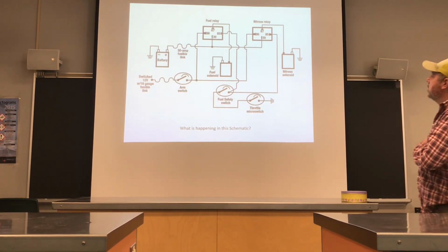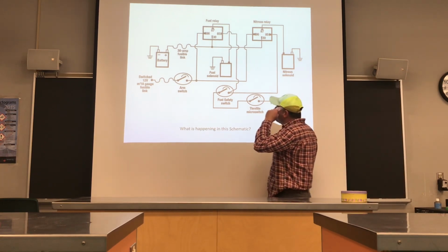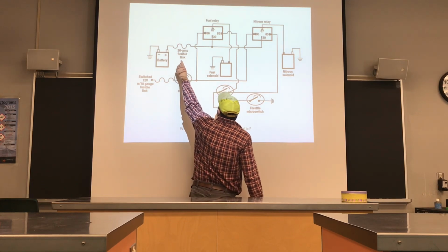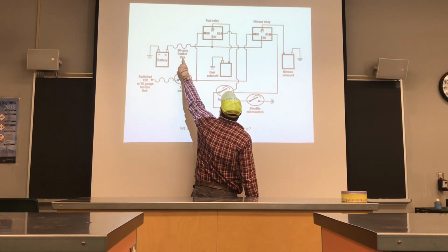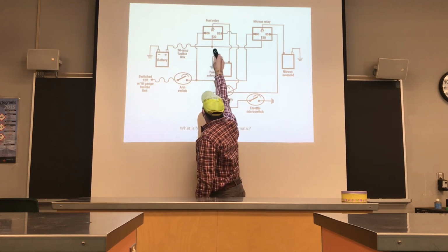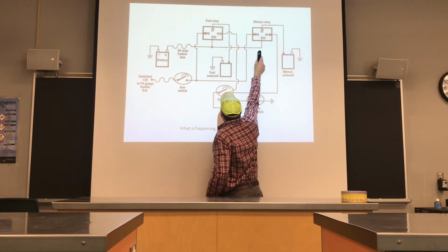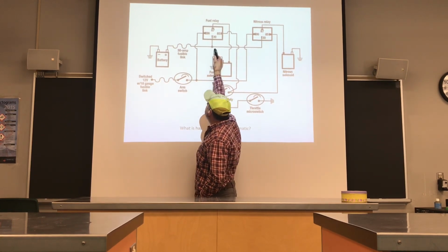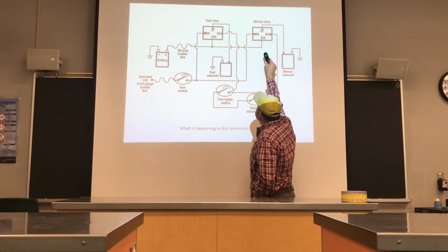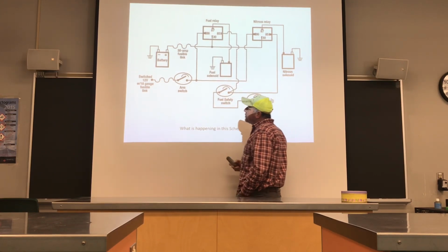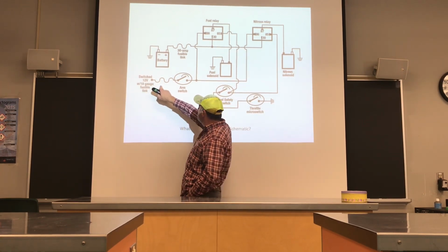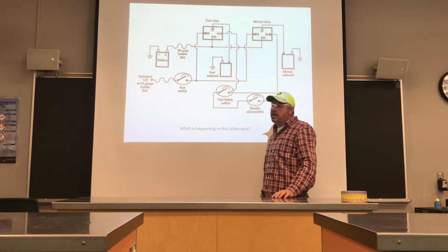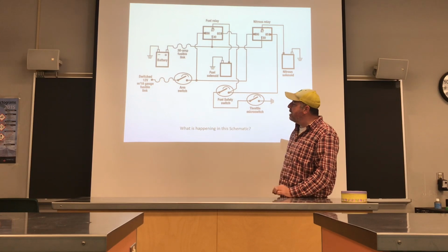Another example here, we have two relays. We have a battery power fusible, so we have a fusible link here. It's 30 amps, so it's supplying constant power to pin 30 on both relays, which tells me that there's basically 30 amps of power at the ready on pin 30. We're going to use our switch, 12 volts, right through a fuse, and this is going to be basically an arm switch or a safety switch, say for example in the cab.